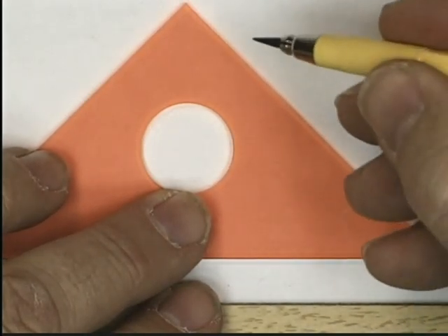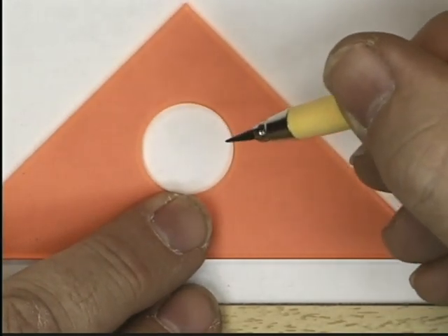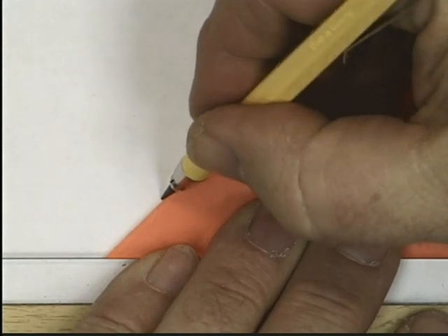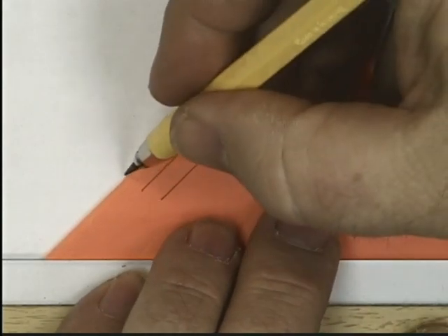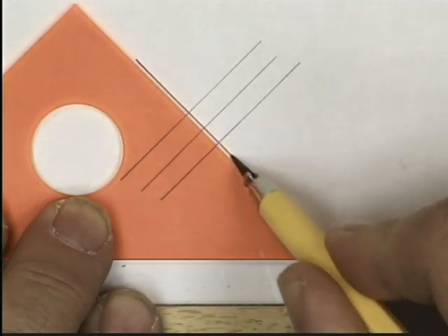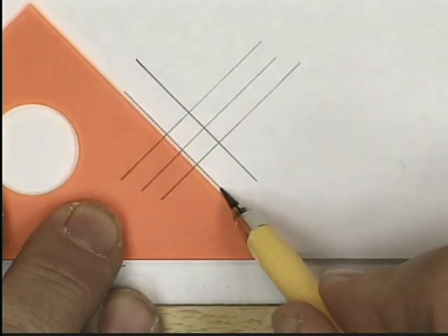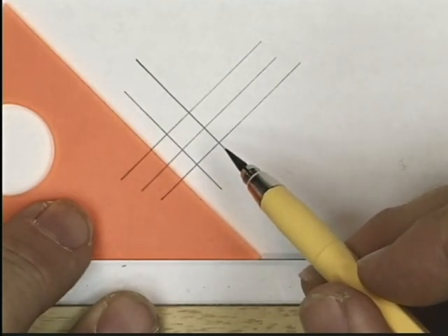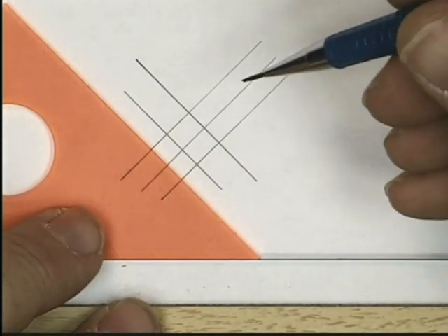So the trick is, as you're drawing, you rotate the pencil at the same time, and that has the effect of keeping the lead sharp and keeping your lines uniform. So I'm going to just draw a few thin lines here, and I don't know if you can see that, but I'm twisting the pencil a little bit each time I draw a line, and that has the effect of keeping the line sharp. Now, these would be construction lines. Actually, they're a little darker than I normally would draw construction lines, but if I drew them the normal darkness for construction lines, you would not be able to see them on the video display. Now let me draw a few lines using the uniform thickness pencil.